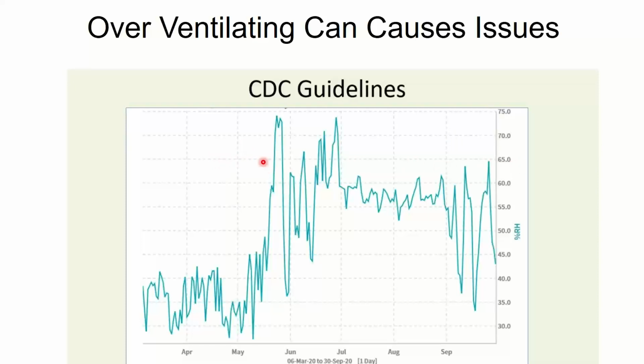We do have 2 ASHRAE standards that dictate relative humidity recommendations. The indoor air quality standard, as I mentioned, which is 62.1, the recommendation is 65% and below. And then we also have ASHRAE standard 55, which is the standard for human thermal comfort. And that standard recommends you keep it below 60% for human comfort. So when somebody asks me what they should be doing, and I know one standard is 65 and one says keep it below 60, I just tell them keep it below 60